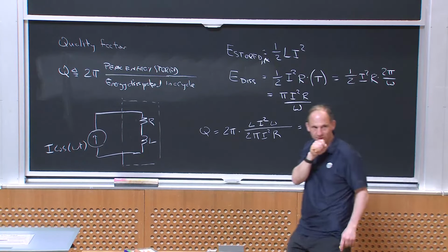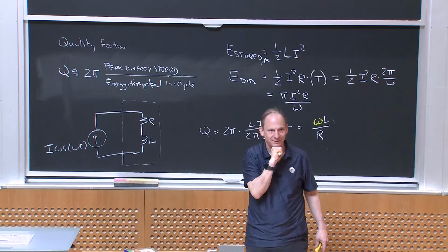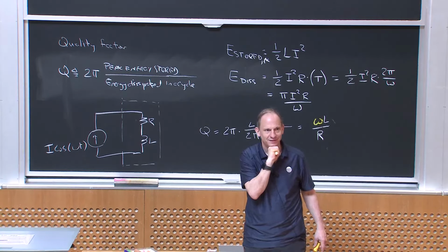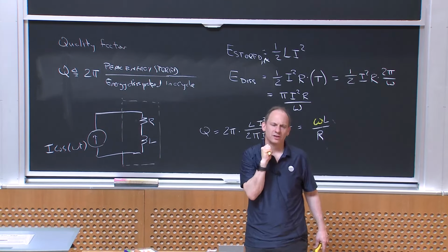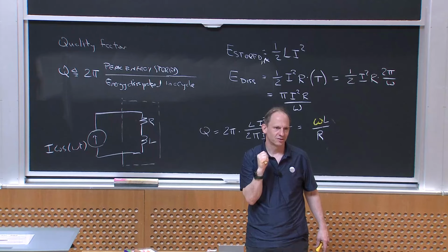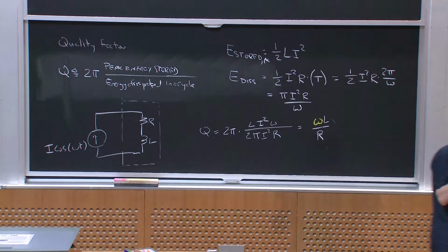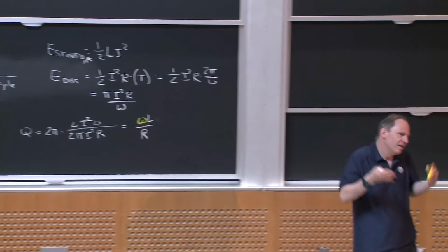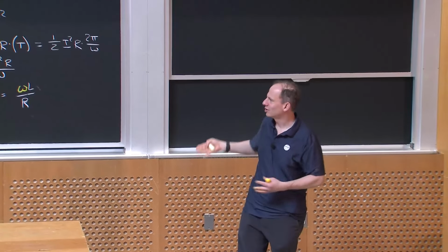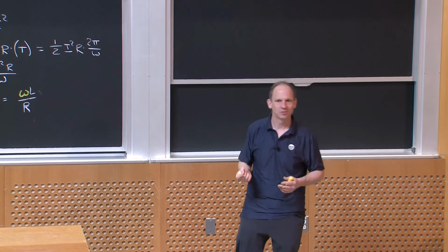Yeah, Julia? Does this definition for Q still work if the drive signal is AC but not sinusoidal, like a square wave or triangle or something? Yeah, usually they don't. Usually you define it under sinusoidal drive conditions. I'm not sure if anybody ever came up with some other definition, but usually that's what's intended. You know, sinusoids are, for LTI systems, their eigenfunctions, so that's what we usually worry about.